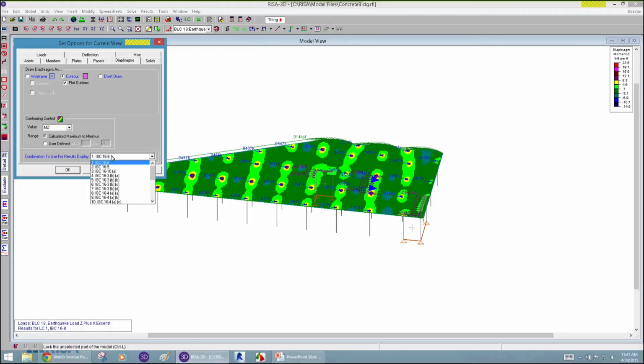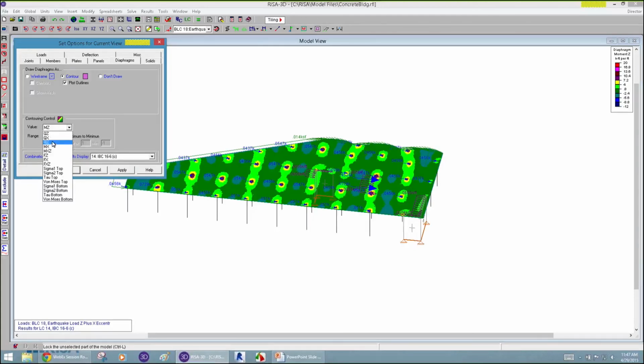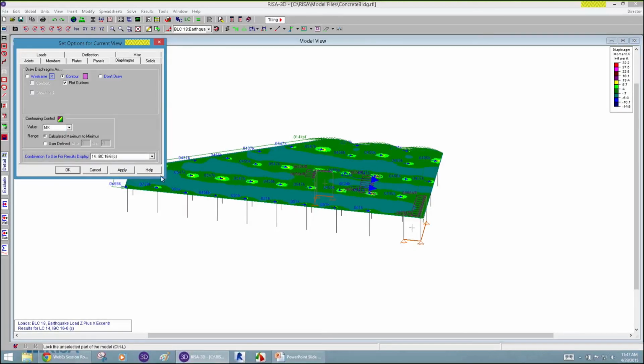We can flip between different categories. So obviously the load combinations that govern, we would want to flip through and make sure that we are finding the maximums for that. I can jump to MX, and so this is a two-way slab. So I see that classic two-way slab directional loading where I'm seeing the moments distributed there in the two directions.